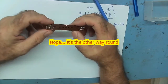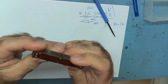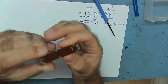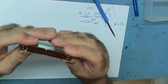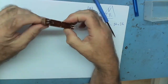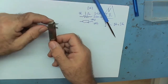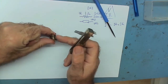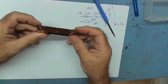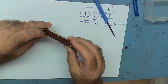This is the last one of these, then we've looked at enough resistors now. This one's marked again. Can I see the markings on that one? Not enough light. Oh, it's upside down, not the right way up. V50K AK2. Yeah, 50K will be the value. This is a slider resistor, which is just the same thing as that, but goes in a line. These twin gang ones, by the way, are often used in stereo, so it alters both channels at once. Again, this is twin gang, so you've got two connections at both ends. You've got two lots of sliders in here.